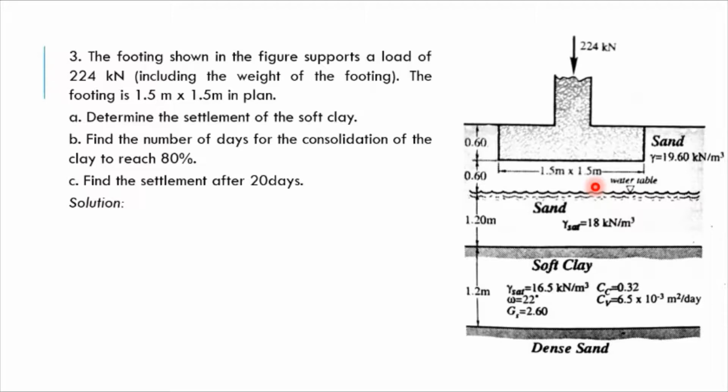So how are we going to solve for the settlement of the soft clay? In this case, there is no given influence factor or anything about elastic settlement. It was not mentioned that the clay has elastic settlement due to the footing. So none. Therefore, we have to solve for the primary consolidation settlement.